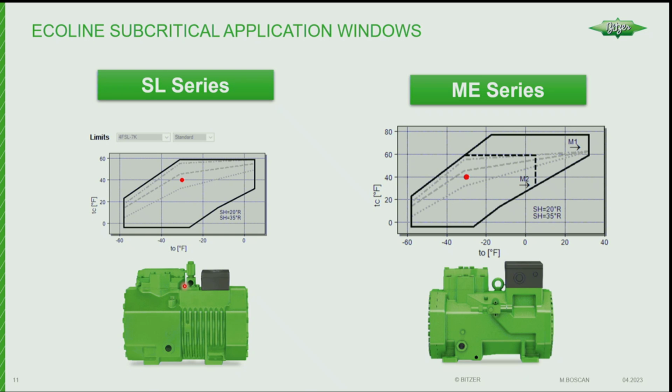What it's doing is protecting the system. Say you close the service valves and you didn't pump out or pull out all the CO2. If it gets hot, that CO2 pressure is going to go way up and past the 770. If you don't have a relief valve, something's going to give, right? So that's what that relief valve is for. When it's operating and you have the valves open, that relief valve is out of play.